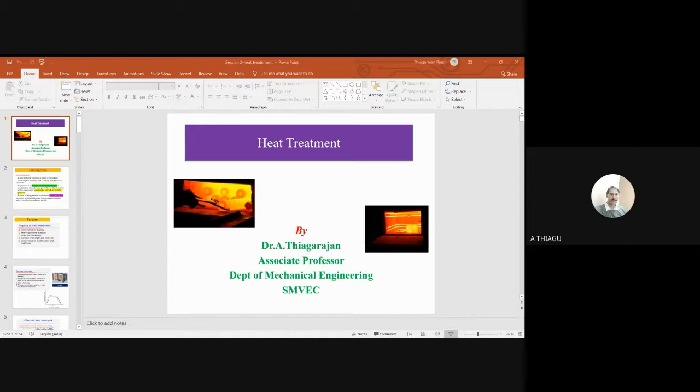Okay, so what will happen? The softness and ductility will be increased. The main applications of process annealing are steel wires, sheet metals, channels. These are good applications for process annealing. So any casting product, you can prefer the process annealing operation. Is it right? So now you look at stress relief annealing.